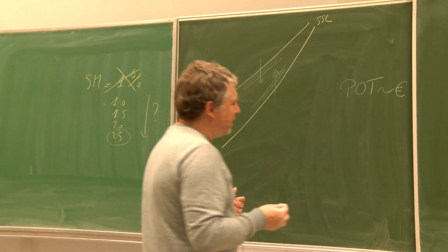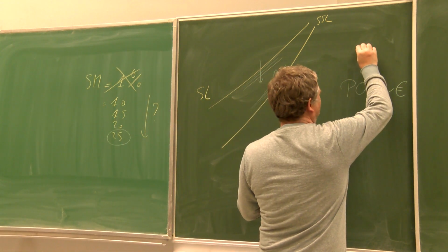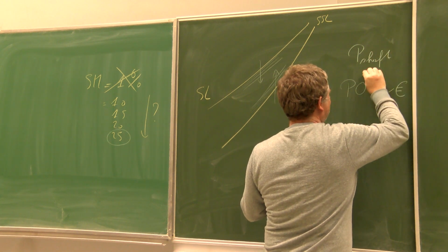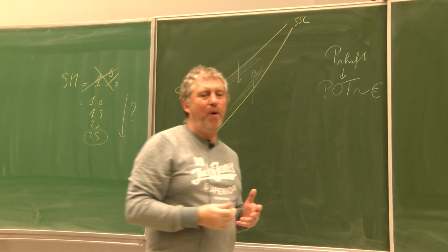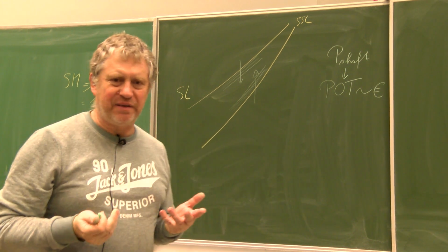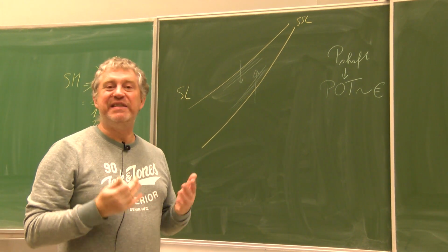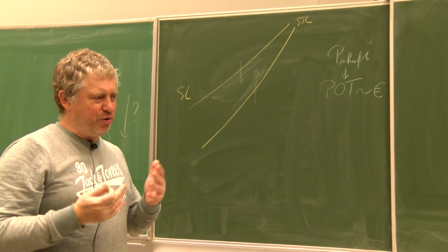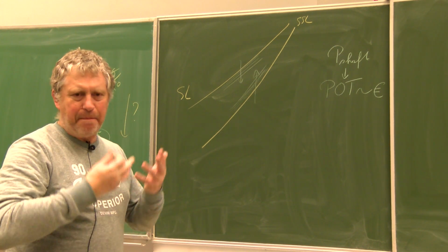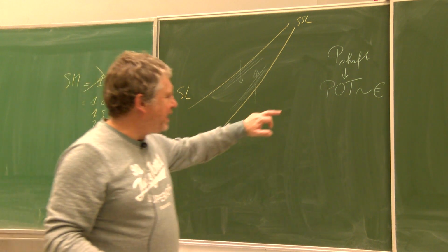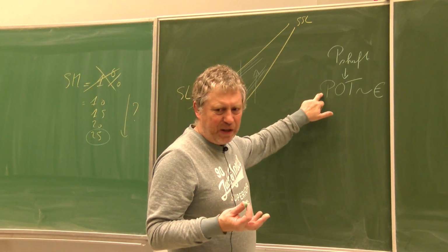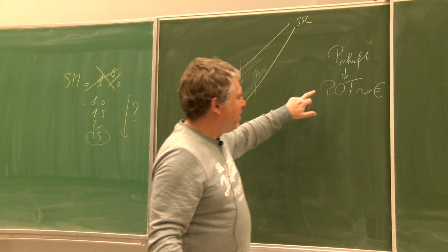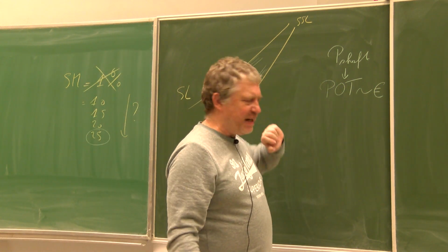But the problem is that the power on the shaft, from which you extract this PTO, is decreasing with the altitude. So when you are going to altitude, you have a huge difference in power on the shaft, but you take the same amount of kilowatts to drive the accessories. So the percentage of that compared to this is increasing.